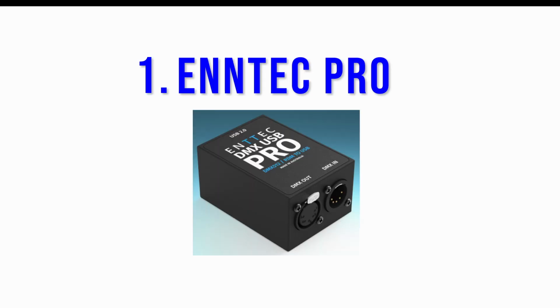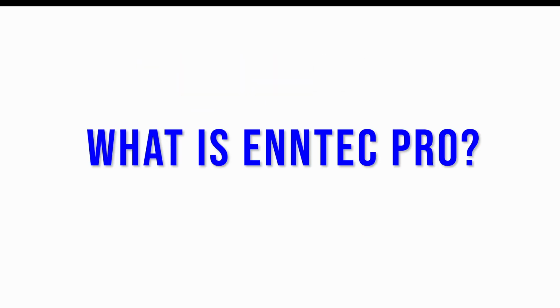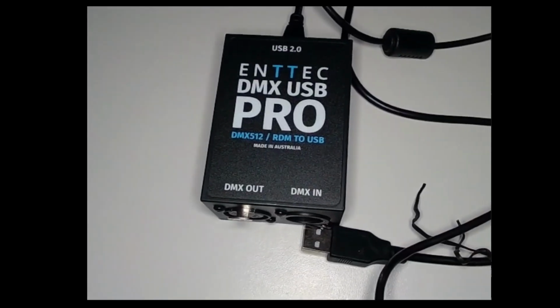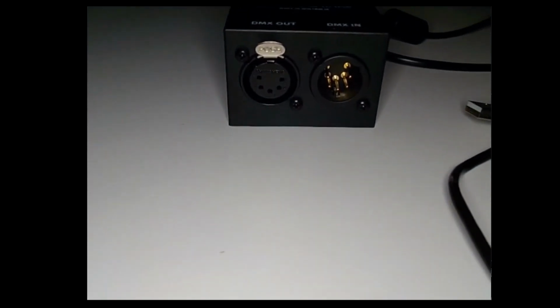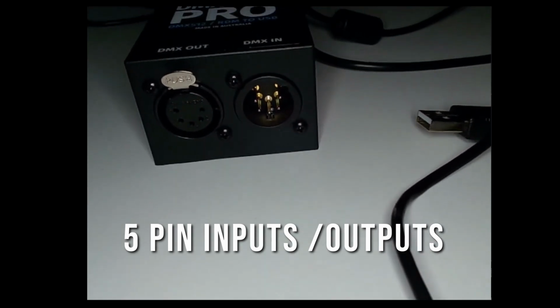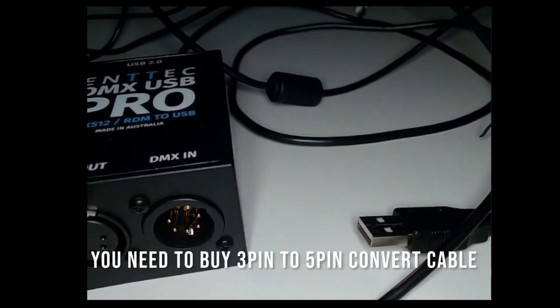The first one is the Enttec Pro, not Open DMX. Be careful, because TouchDesigner only supports the Enttec Pro. So what is the Enttec Pro? Enttec Pro is an interface with USB, and it is fast, stable, and industry standard. This is the DMX USB Pro, but you need to be careful here. The Enttec DMX Pro has a 5-pin output and a 5-pin input. So if your DMX beam has a 3-pin, you need to buy a converter.